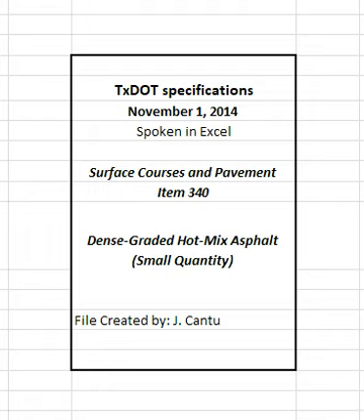The engineer may have the cores transported back to the department's laboratory at the HMA plant via the contractor's haul truck or other designated vehicle. In such cases where the cores will be out of the engineer's possession during transport, the engineer will use department-provided security bags and the roadway core custody protocol located at http://www.txdot.gov/business/specifications.htm to provide a secure means and process that protects the integrity of the cores during transport.